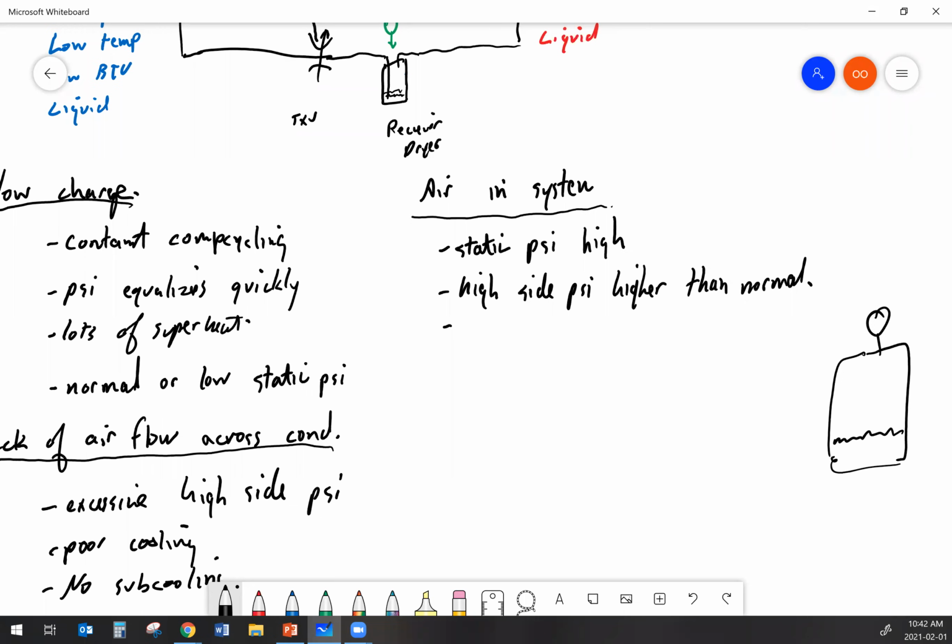So if I take that container of refrigerant and I stick it outside and it's 20 below outside, remember what I said, at 20 below, the pressure is going to go all the way down to 0 psi. That's the boiling point at atmospheric. But if I was to take that same tank of refrigerant and cool it down below 20 below, let's say it gets down to 30, 35 below outside, that means that I end up in a vacuum inside that container because the refrigerant has collapsed down below its boiling point.